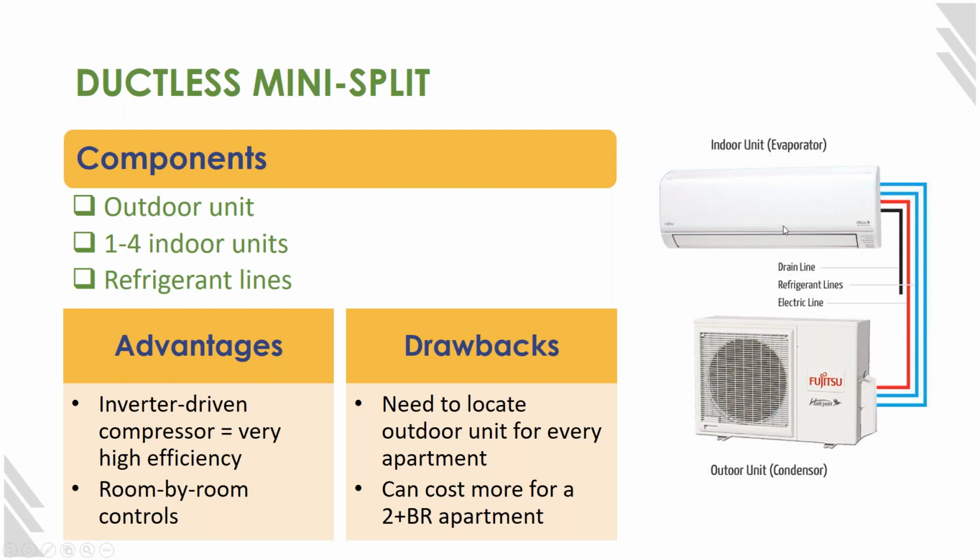They'll do a ducted fan coil because at that point, the cost of having 4, 5, 6 of these indoor units is more than the cost of one ducted unit inside and then running the ductwork and softening to the different bedrooms. So sometimes there's like a cost tipping point with a number of apartments. So that's something to look at on your project and to think about.